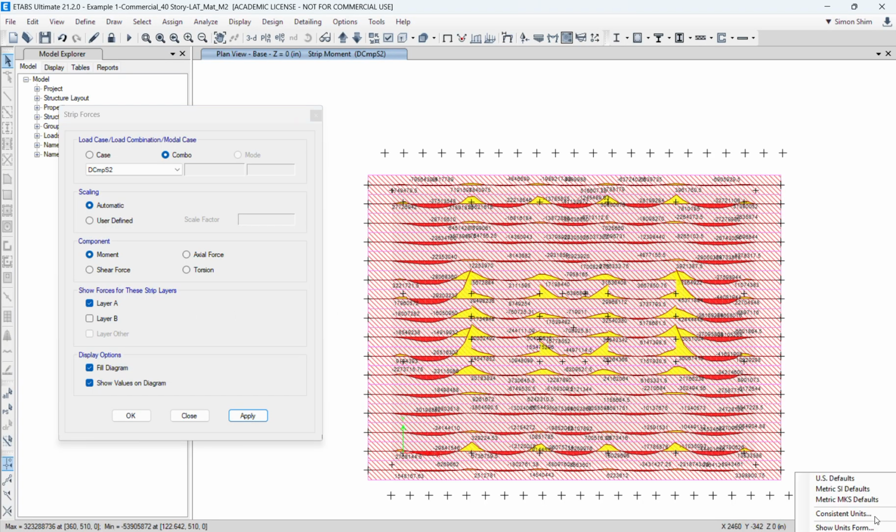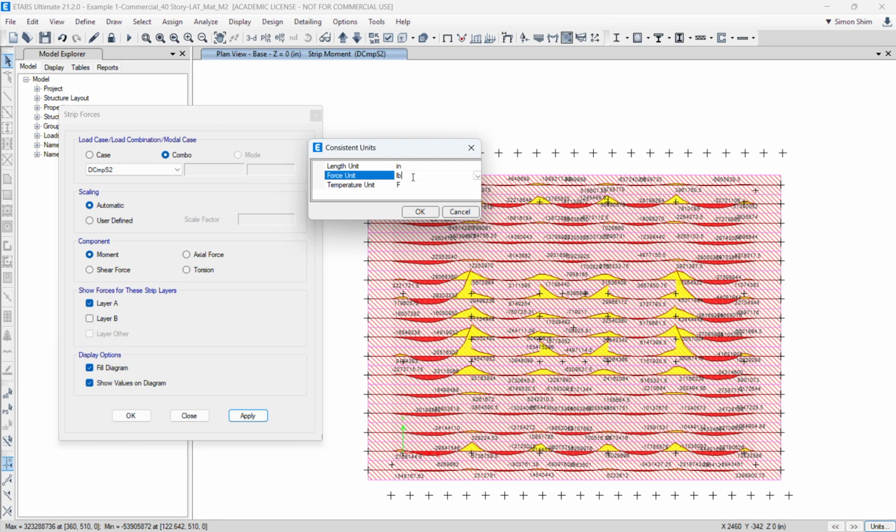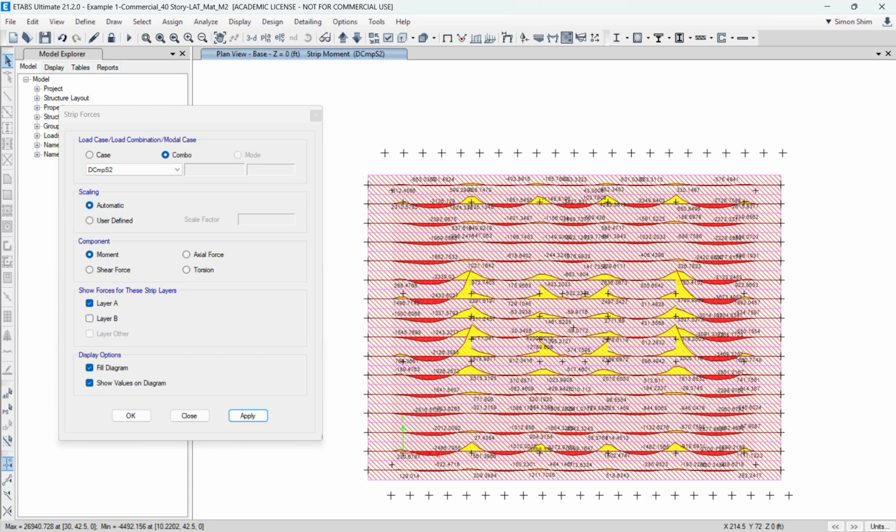Okay, so yeah, actually you can see in a general sense the bending moment diagram for the mat on continuous spring. So you see a series of compression and tension. This totally depends on the mat, the continuity over the soil, right?